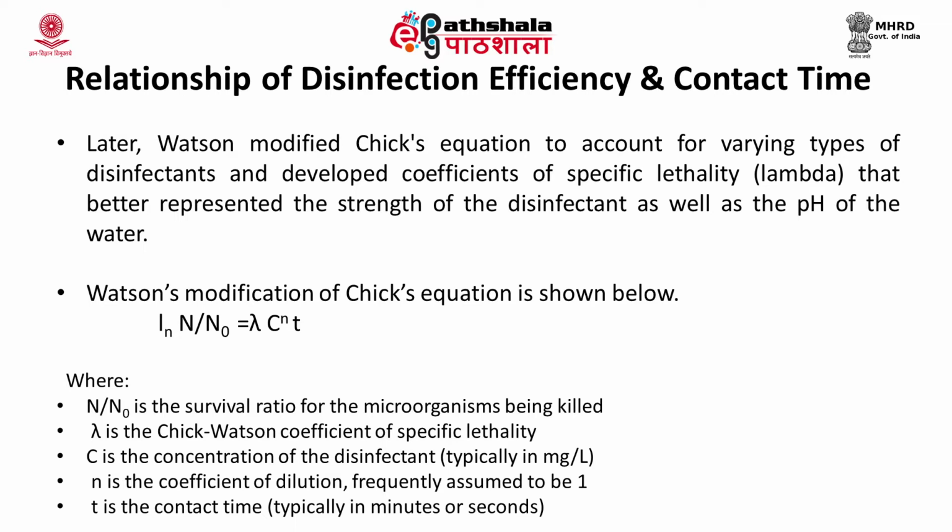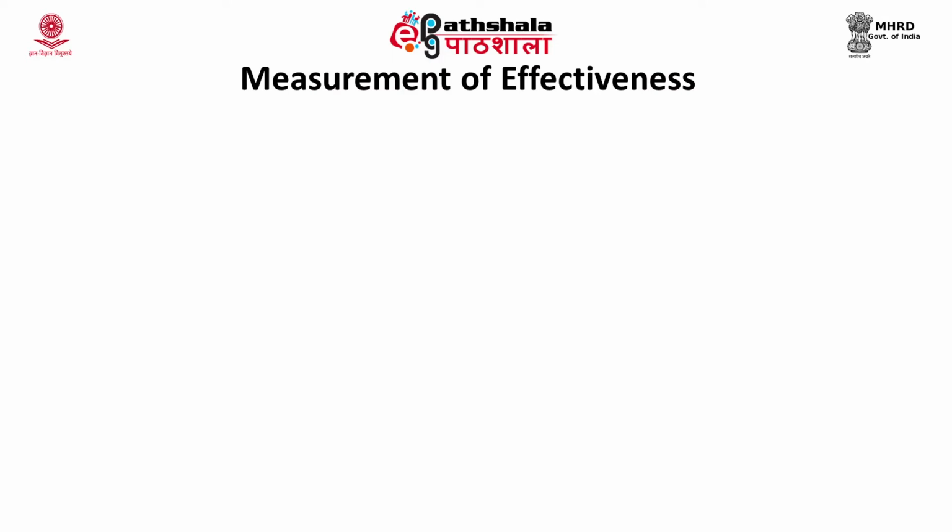The next parameter affecting the efficiency of the disinfectant is the temperature at which the wastewater is present, the type and the population of the microorganisms present in the wastewater, as well as the pH and ionic strength of the wastewater. Now, coming to the measurement of effectiveness of the disinfectants.